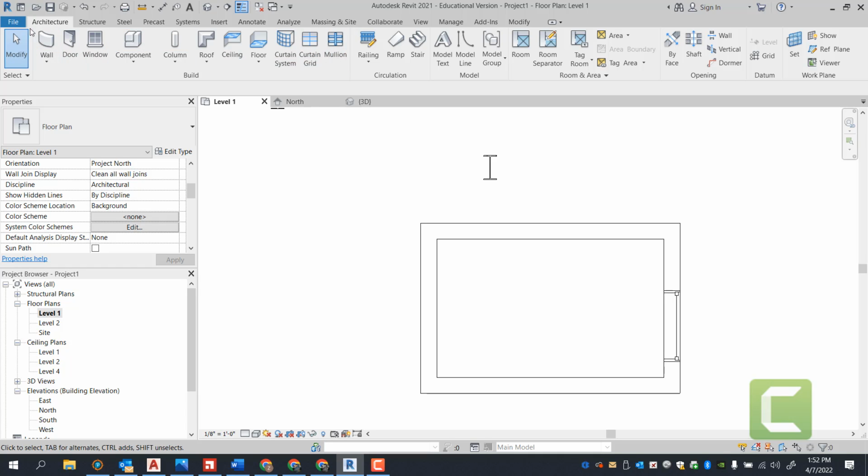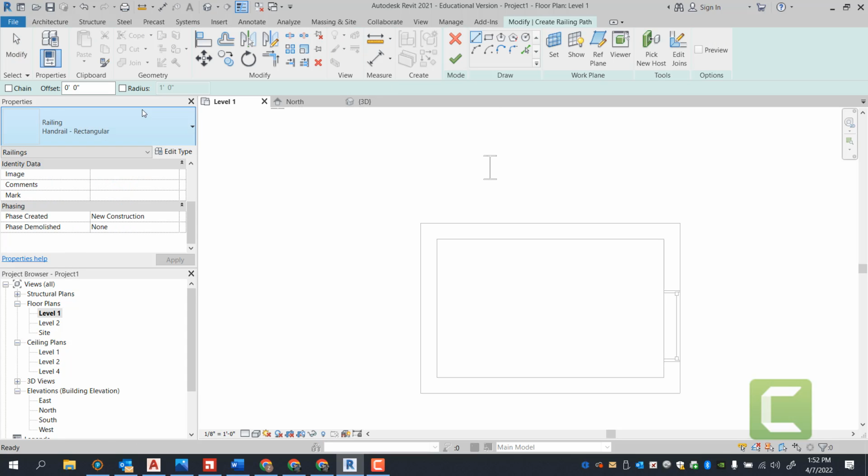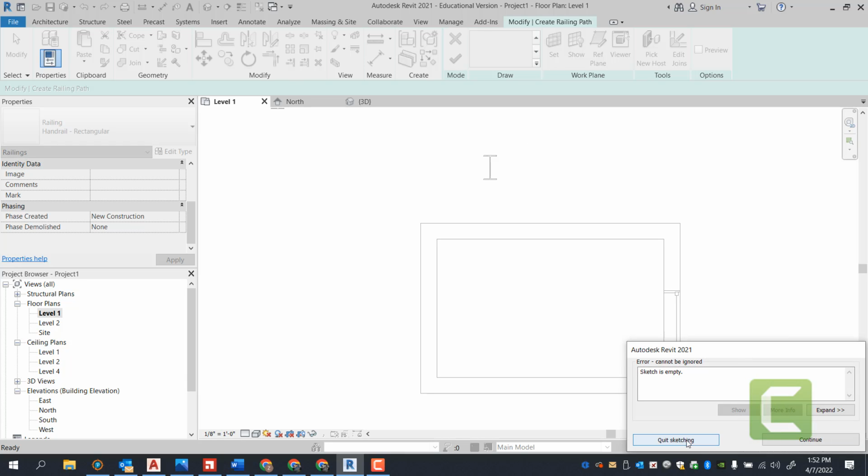So these are going to become your best tools. When you click on railing, understand the difference between sketch path and placing it on a stair or ramp. Do not mistake those two, right? Sketch will cover the whole base. If it specifies an offset, specify that offset. Know which side you're offsetting to.